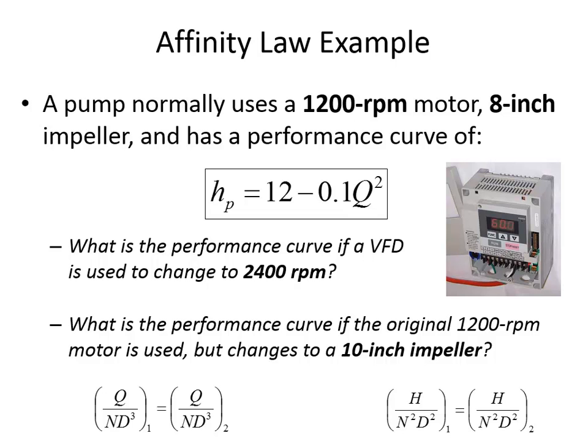First of all, we'll look at the rotational rate. For 1200 RPM, how many radians per second is that? Do you remember what the conversion between RPMs and radians per second is? Remember, there are 2 pi radians in 1 revolution, and there are 60 seconds in 1 minute. So how do we convert from RPM to radians per second? Multiply by 2 pi to get the radians per revolution, and then divide by 60 seconds per minute.